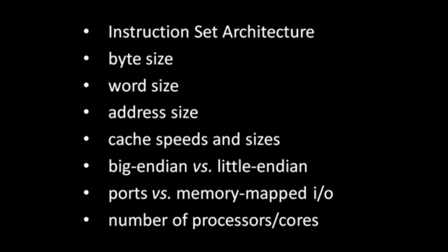The advantage of stuffing multiple cores into one single package, rather than having multiple packages, is that it's relatively cheaper and better for power management and system cooling. Most new consumer PCs today contain one processor with 2 or more cores. While some expensive systems, namely servers, still use multiple separate processors, those processors now typically have 8 or more cores each. While it is possible for a single program to accelerate its performance by utilizing more than one core, doing so effectively can be very tricky, as we'll discuss later when we talk about concurrency.